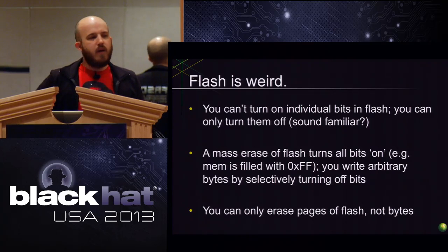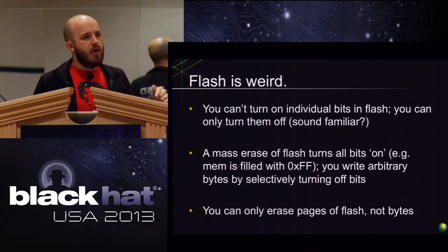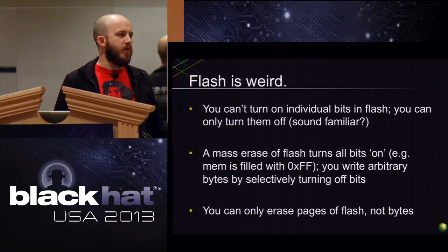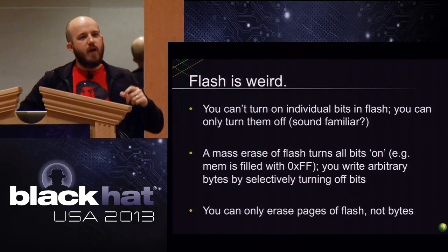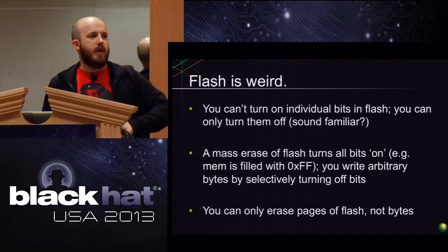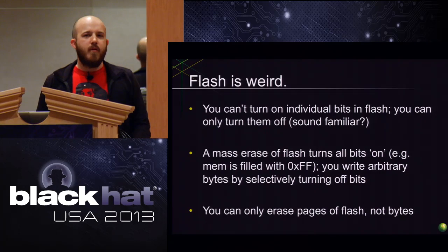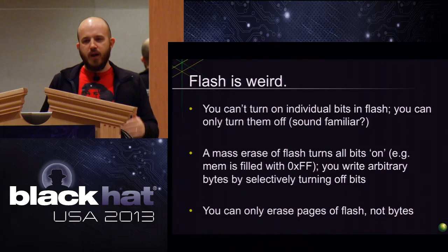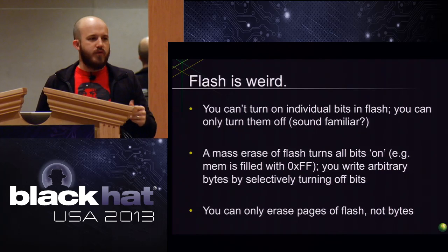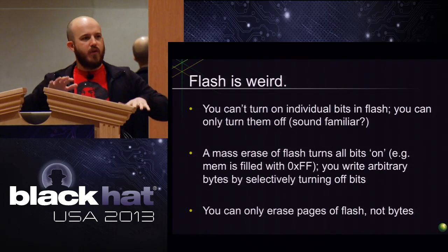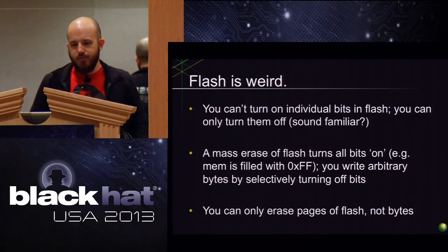What that means is that if you want to make a modification, you have to reset it to FF first before you can put an arbitrary piece of data in it, or you have to find a place in code memory that's already full of FFs. It's very different than normal RAM or what we think about on hard drives, where you can just push something and say go do that. If you don't know what you're doing and you don't know the state of it beforehand, then random writes will just fail because it can't create that state, because it's all a series of which bits are turned on and which ones are off.